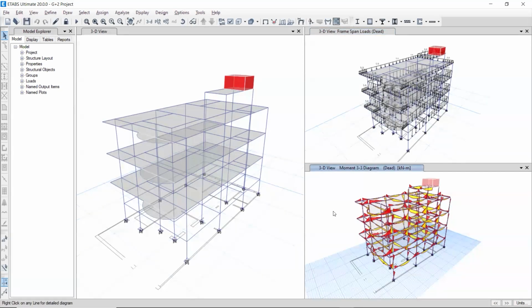For small scale projects like G+1, G+2, you can ignore P delta and these advanced processes. We have a separate course for high-rise buildings, very high-rise building P delta analysis. This is a separate course that you can go for. Our team will discuss that separate course with you. But for small buildings, G+1, G+2, G+3, even G+10 or 11, 12, P delta effects will be minimal. You will see in our advanced courses, we have talked about it. So for small scale projects, you can stick with the earthquake and wind analysis.